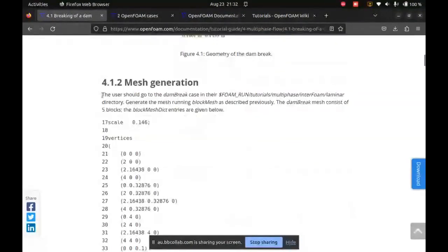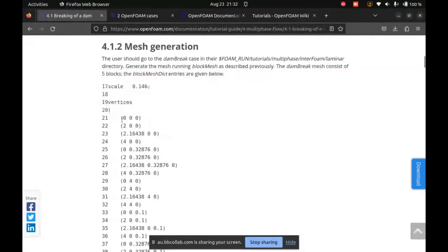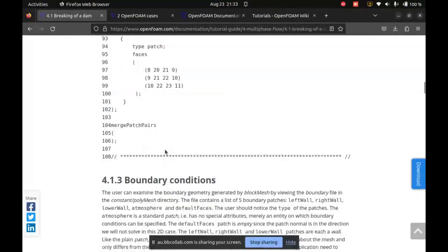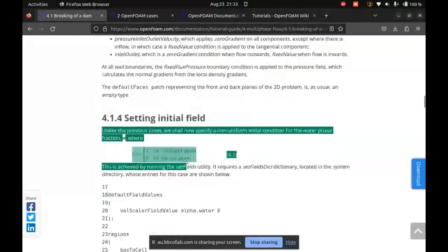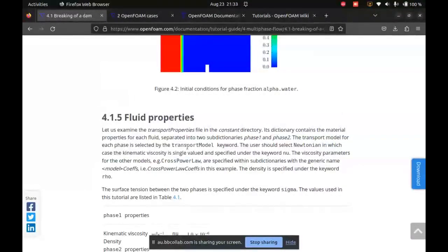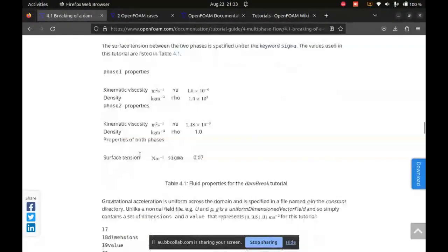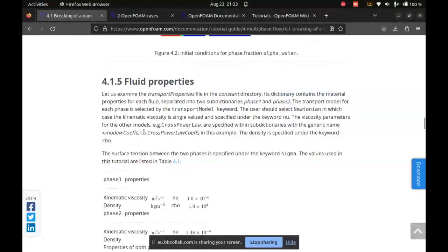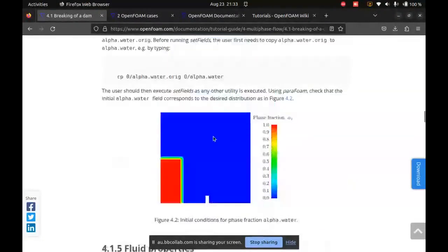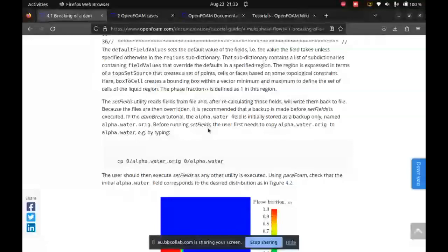So yeah, right. If you look at the top on the web, let's look back to the web, it goes into a lot more detail about what we just did. We ran blockMesh, and this is the blockMesh dictionary. And we ran the boundary conditions, and we ran the initial fields, and we ran the solver. And it goes into more detail on which solver we're using, and what the values of the simulation are, what the solver properties are, whether we're using Gauss-Seidel, or Jacobi, or BiCGStab. It doesn't matter in this case, but trust me, it matters when you are working on the bleeding edge and things diverge. Yeah, that's very useful.